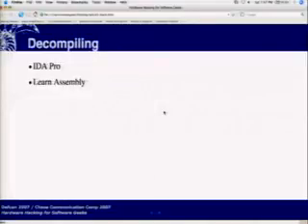The flash dumper thing I was talking about up there, that is for accessing more modern stuff, these 48-pin, thin, small outline package flash chips. It turns out that XD cards for cameras and smart media cards for cameras are basically NAND flash in a funny package. They're exactly the same interface, and you can use one of them to build a flash dumper that you can just clip onto the chip and depending on the electrical characteristics of the board, dump the flash via a USB cable.